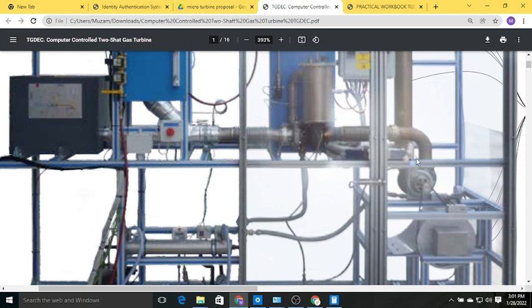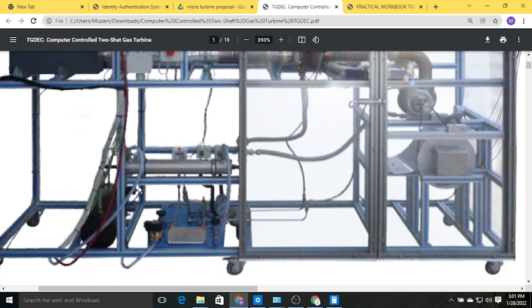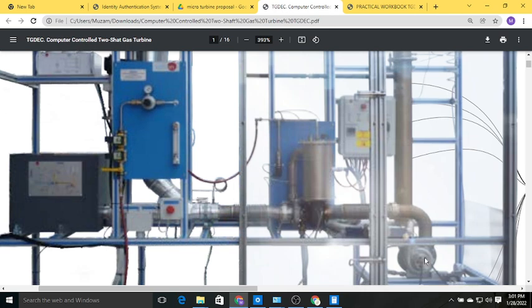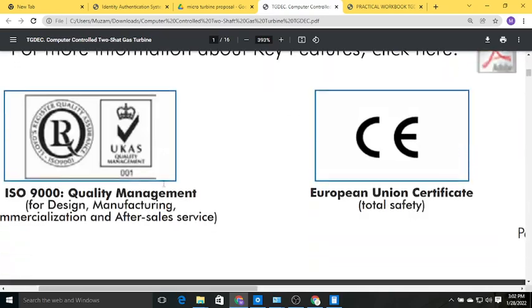Then the hot oil, after getting hot from this high speed turbine and compressor shaft, goes to the heat exchanger, cools down with tap water, and is collected again in the sump to recirculate. This turbine is working at an RPM of around 120,000 to 130,000, but the secondary turbine is generating power, so it is a low RPM turbine. I'll show the parameters, like 30 to 40,000, and that is further reduced to 3,000, 4,000 by the belt and pulley system. Okay, so this is the system.